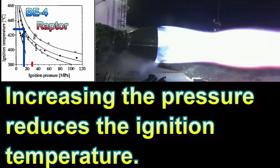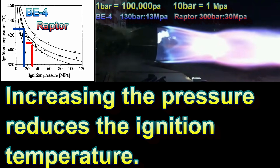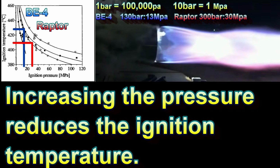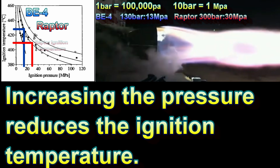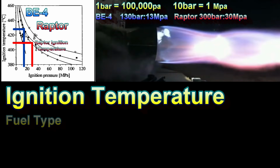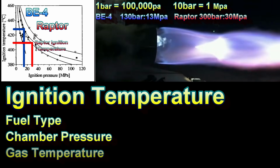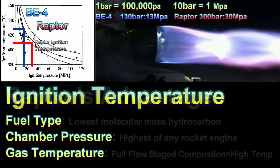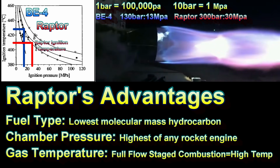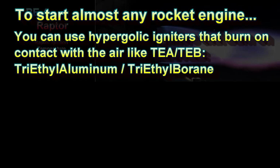The Raptor rocket engines operate at about 300 bar. A bar is 100,000 pascals, and this comes out to 30 million pascals or 30 megapascals. That would be about here. So ignition temperature is determined by the type of fuel, the chamber pressure, and the temperature of the gas. When hot methane and oxygen come together in a Raptor, a simple microwave emitter might be enough to get it burning. For our rocket, if we didn't want to use a pyrotechnic device, we could use a chemical that burns